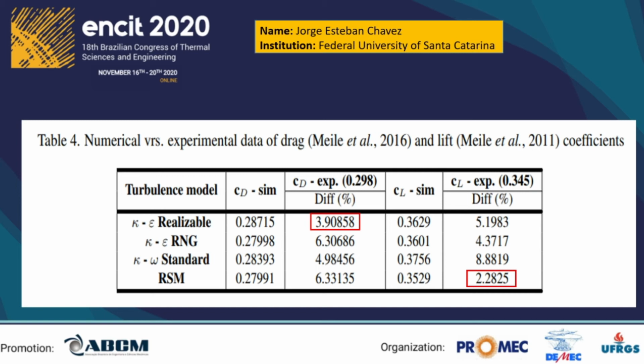On the other hand, the Reynolds stress model is one of the most elaborate types of turbulence models, solving 7 transport equations for 3D cases. It was also the most computationally time consuming. Thanks to its great ability to predict more accurately the different pressure gradients around flat surfaces and streamlines, it was observed that for the Ahmed reference body, this turbulence model showed greater proximity to the experimentally calculated lift value.